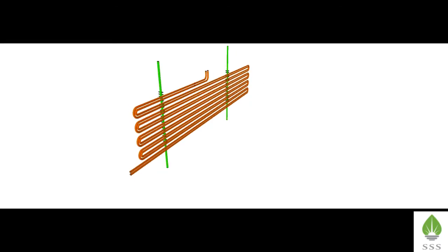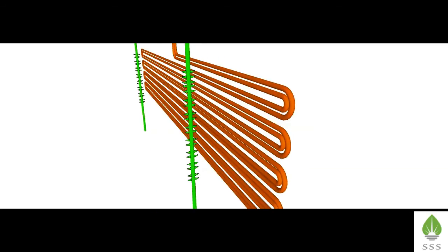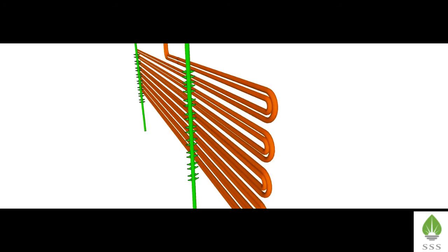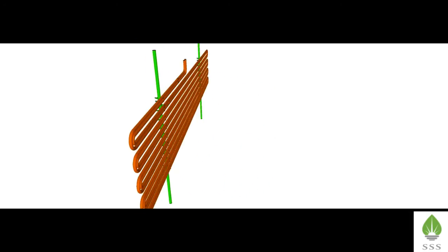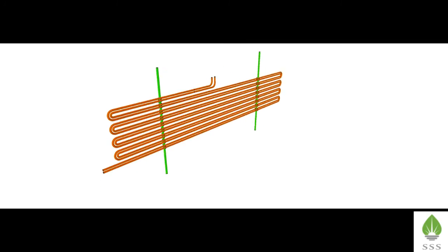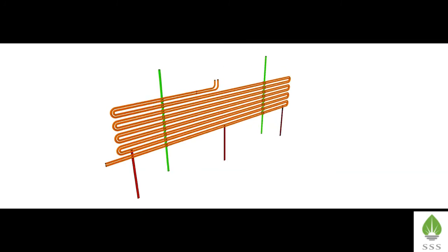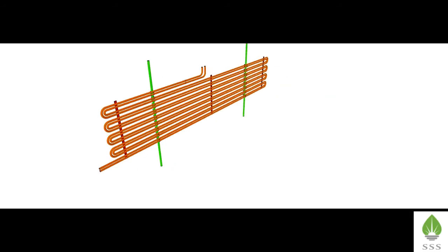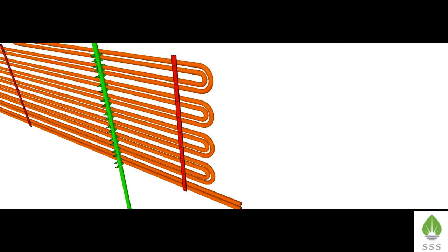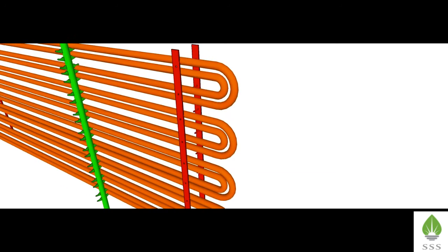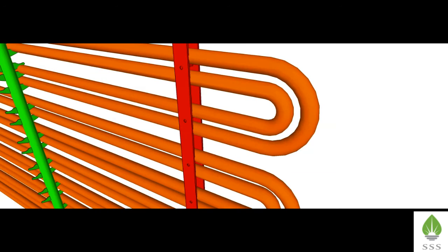Primary superheater horizontal tubes consist of series of coils. The pitch of these tubes is maintained by the attachment provided on the stinger tubes. The stinger tubes are provided with attachment on both sides. 2 sets of coils are attached to a single stinger tube. Primary superheater horizontal coils are also provided with anti-vibration bar. It consists of a rectangular plate provided with holes according to pitch of coil. Another rectangular plate consists of pins welded according to the pitch of these holes. Insert the pins through the holes and weld the pins.